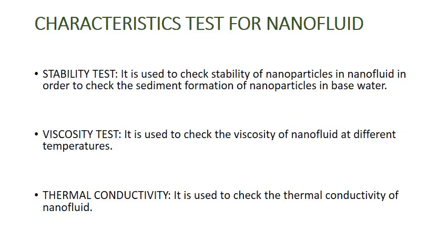These are the characteristic tests for nanofluid. The stability test checks the stability of nanoparticles, in order to check the sediment formation of nanoparticles in the base water. Viscosity is used to check the viscosity of nanofluids at different temperatures. Thermal conductivity is used to check the thermal conductivity of water. From here we can determine the thermal conductivity of the nanofluid, and then we can compare it with water.